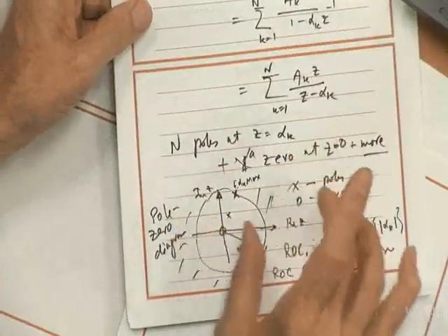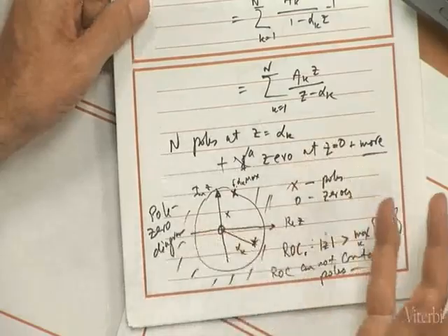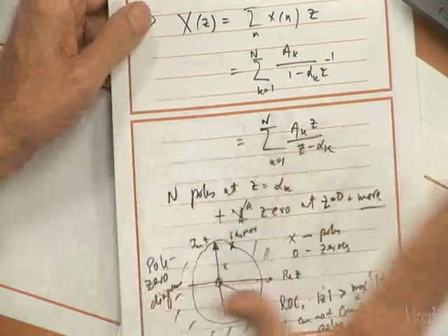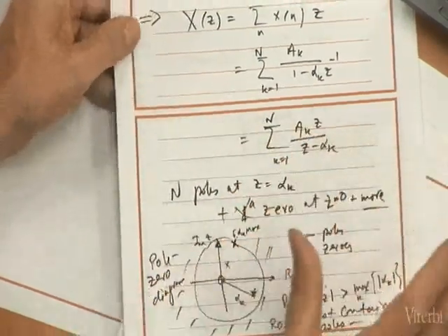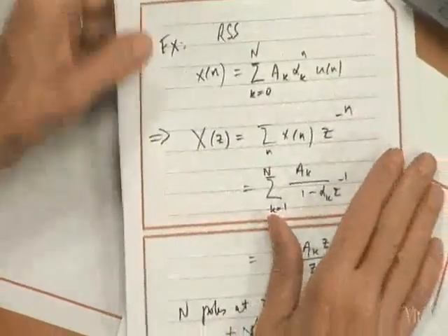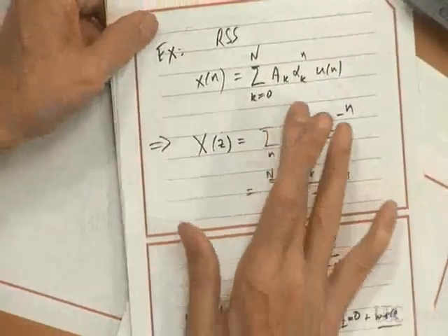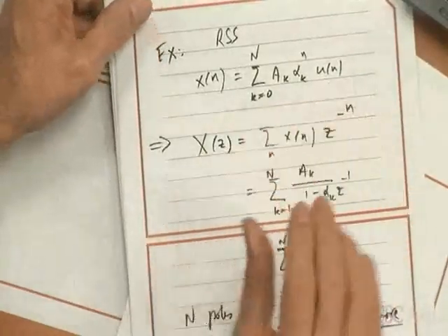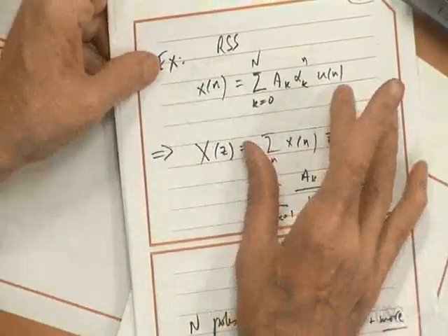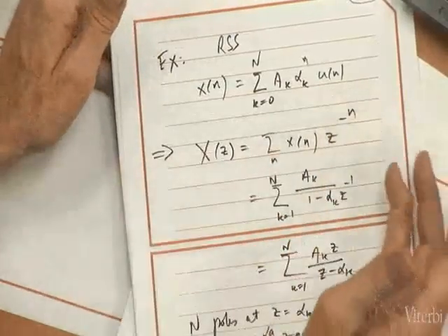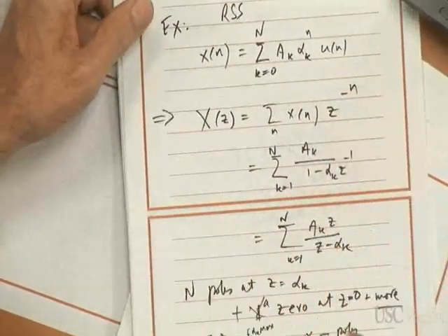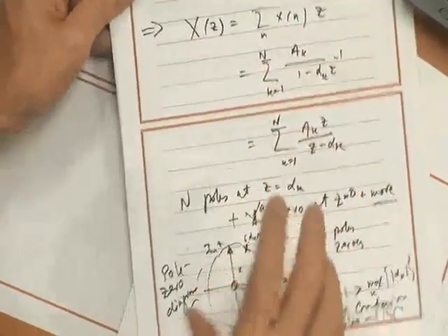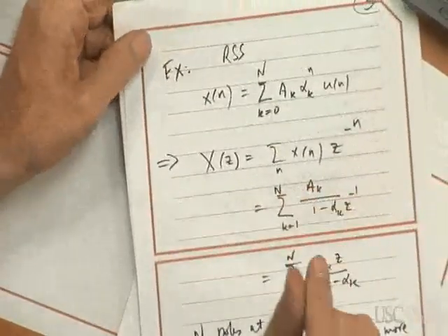And the Z transform may converge, we say it includes infinity or not. By that I mean it may converge at infinity, or it may not. Very interestingly, it depends on if the sequence is causal or not. If the sequence is 0 for n less than 0, then the Z transform actually does converge as Z goes to infinity. So we would say the region of convergence would include that.